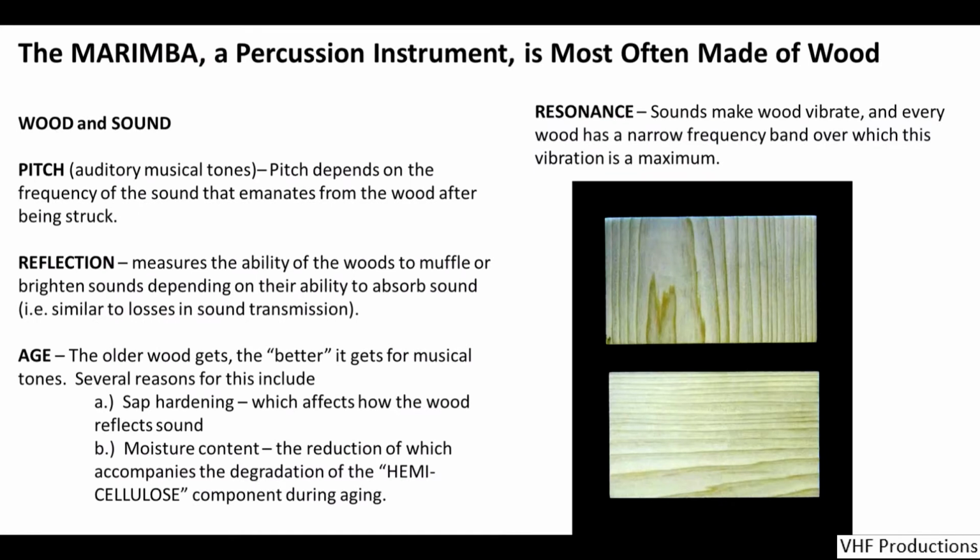For the marimba, we want to make the keys resonate. In other words, we want to make the wood vibrate in a very narrow range of frequency. Each key has that resonant frequency tuned by the span length of the key. The keys are all made of the same wood, and the frequency generated by striking the key is then tuned based on the distance of the span supporting the key, as well as other aspects of the key design that would affect its geometry, mass, and so forth.